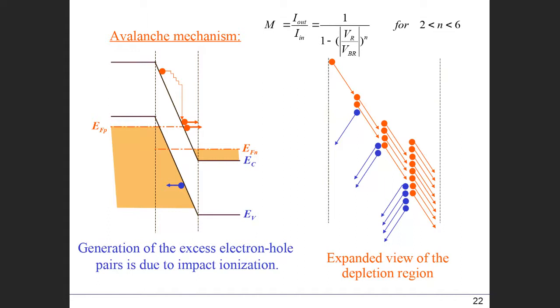For example, to describe this in an image here, in the PN junction diode you have a depletion region which has an electric field, so the electric field is going in like this. When an electron, let's say, goes into this depletion region, since the electron is negatively charged, it is accelerated through this structure. When it accelerates, at some point, let's say this electron hits the body of the silicon and gives energy to the silicon, and then the silicon frees an electron and hole.